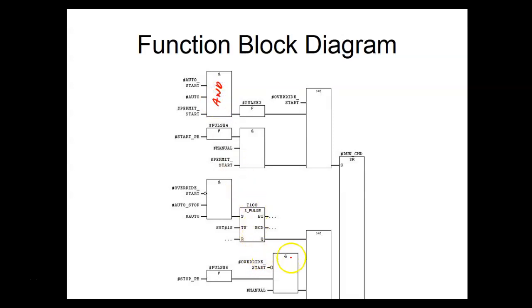I don't see any ORs. So all we do is it says, okay, if this and this is true, then this right here would go what? True. So this is just like digital. So if you took digital and you just have to learn these international symbols, this is the way you could program it. You could actually take a digital circuit that controls the device and you could program it into this PLC.